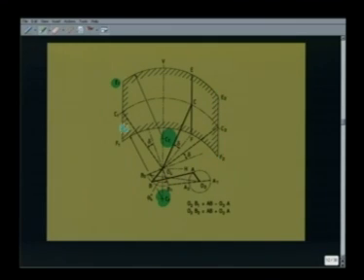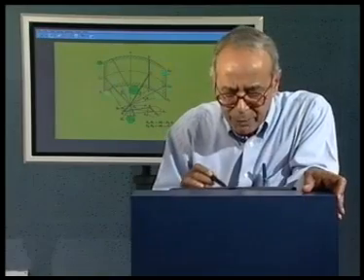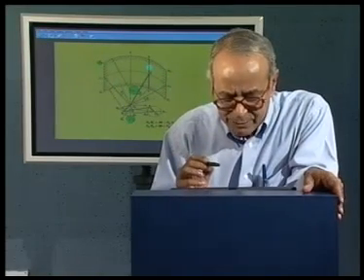E2-F2 and E1-F1. So, with center as CE and radius as O4C, which is the same as CE1, I draw this circular arc. Similarly, with center as CF, I draw this circular arc, and these are the two extreme positions, and the wiping field is what has been shown by these hatched lines. So, we have obtained the field of wiping for this particular mechanism.